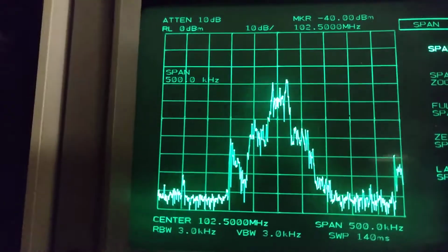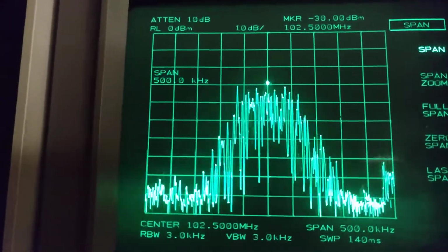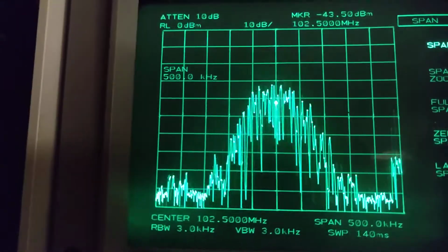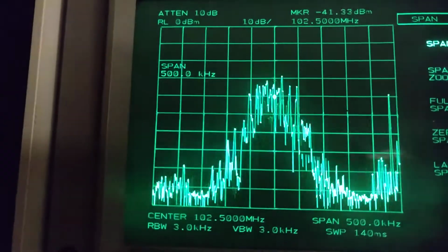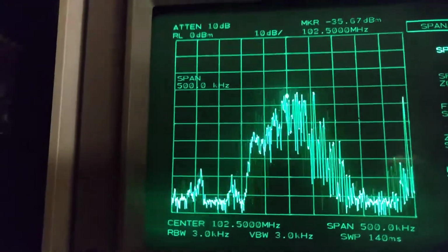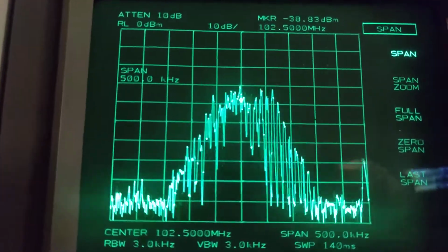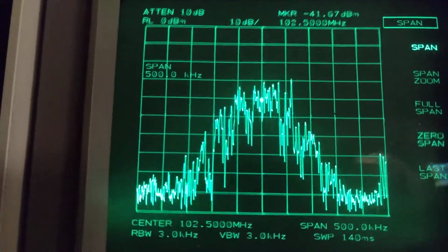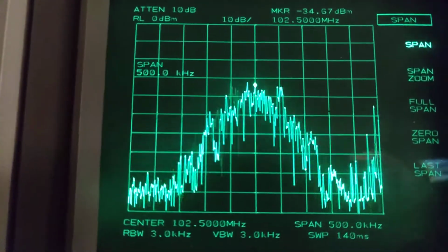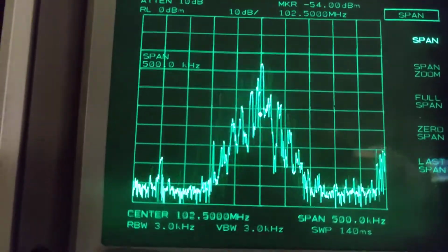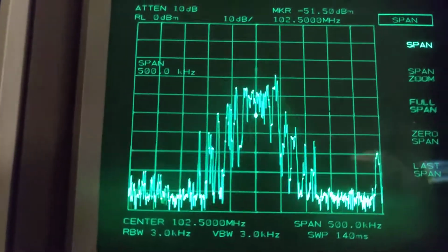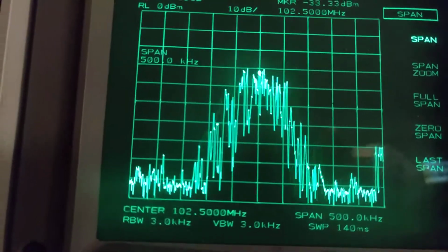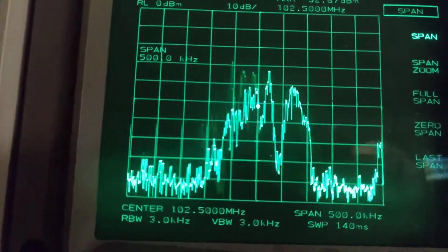But you see that the marker measuring in this configuration is totally erratic and will not give you any good information. It looks like the power is continuously changing, but it is not. Let me show you. If I increase the bandwidth of the spectrum analyzer until it gets all the power, now you have seen that quite without modulation you have the maximum, but with these settings, really the power is also always the same.